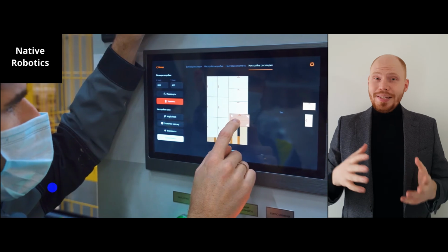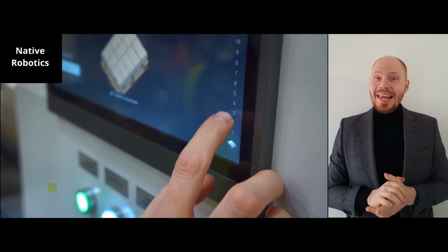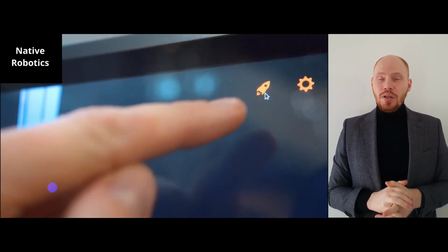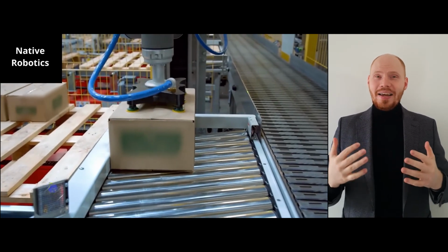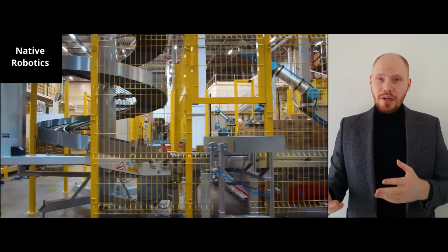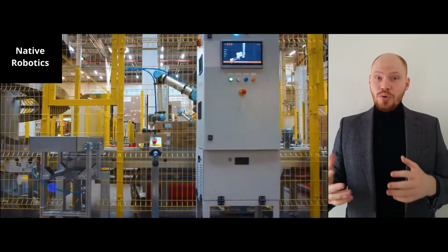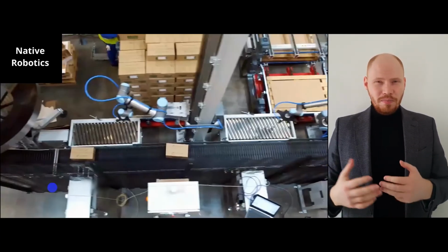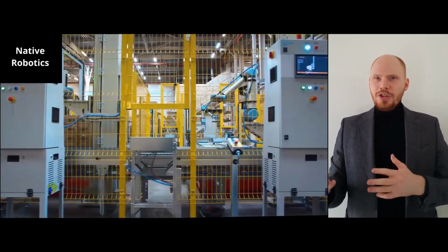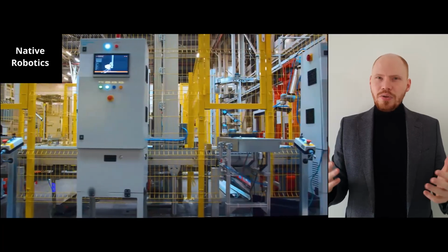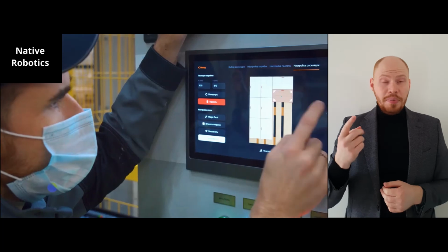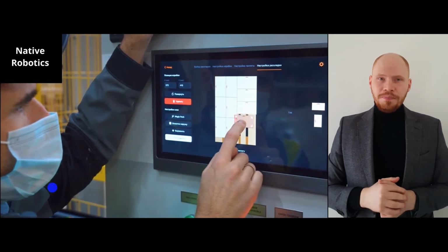This is a project which we did together with an integrator company, ANT, for a leading coffee seller in Eastern Europe. We installed 8 palletizing stations which were interconnected with each other, and each of them used OmniPack to control the robot and the 7th axis. We used a rail-based design as we have to make 7+ feet pallets. Each station has more than 100 layouts inside and communicates with several external devices: conveyors, PLCs, and even AGVs.